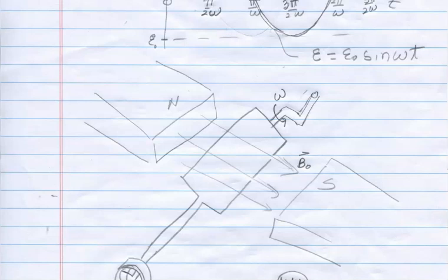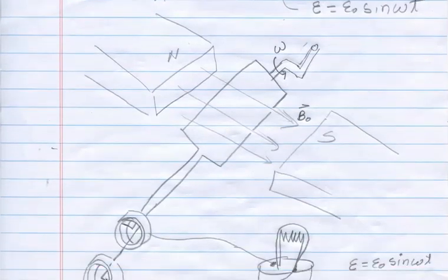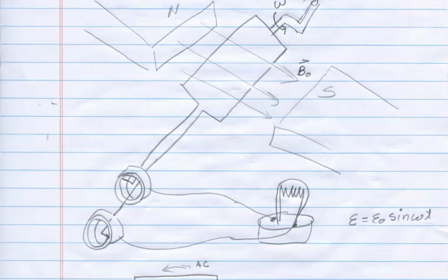But how do you make use of the current that goes there? Well, you complete the circuit in the following way. Along this shaft, you run the end wire out through these 2 split metal rings. One of them comes in and you send it through a metal brush that brushes up against the edge of this one, so as this ring goes around, it rotates here.